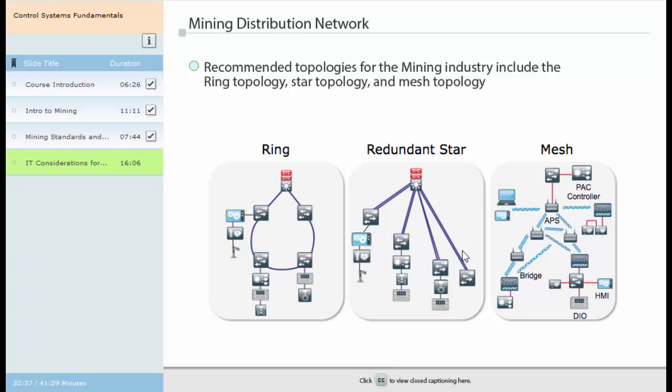The network topology selected for the wired and wireless sensor network largely depends on the area that needs to be covered. Considerations like data redundancy or energy optimization need to be taken into account. Every network topology has its own advantages and disadvantages, but in cases like the mining industry with many phases, such as extraction, transportation, and processing, a hybrid of topologies is frequently in place.